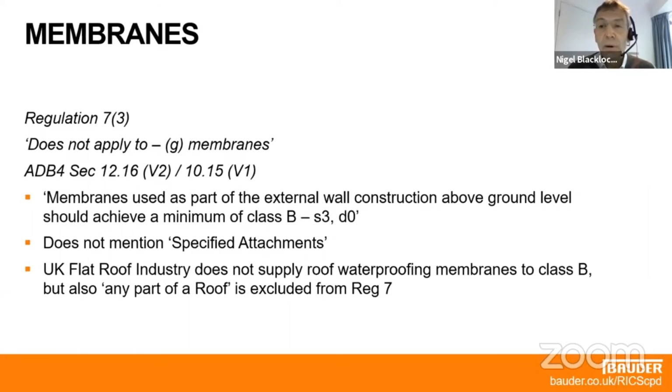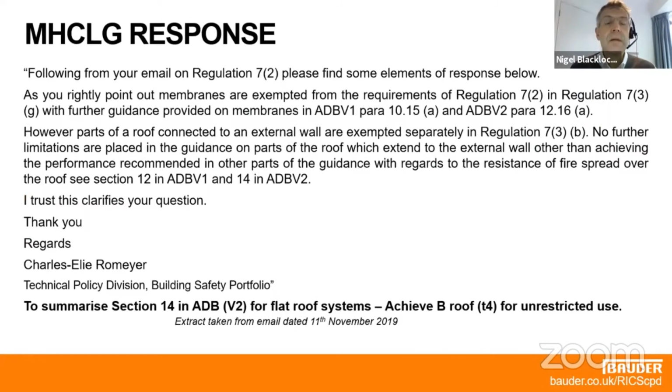As a general point, but a secondary point, the flat roofing industry does not supply flat roofing membranes that achieve anywhere near B. There may be membranes you've come across that might achieve B, but they're not used or suitable to be sealed and used as flat roofing. So that is a common misunderstanding.